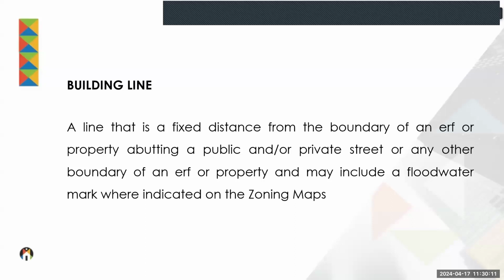Later, it's also a requirement that when it comes to the fire safety distances, we automatically comply with that and do not have to do a lot of calculations to show that we comply. So if you do a relaxation of a building line, basically what happens is that you have to get the next door neighbor's approval. That is the reason for that. But the next door neighbor must remember that in many cases he's given away some of his rights for future development on his property.